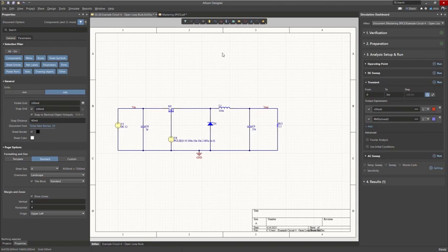So now let's say that everything is good with this design, and we want to make thousands of this design. We want to produce them. So what we want to be wary of is the varying values of my components, because when you get components, they're not always as labeled. For instance, a 100 ohm resistor, if you're ordering thousands and thousands of these components, maybe one will be 100, another one will be 97, another would be 103 ohms. So they're not all going to be the same, and that's true for capacitors, inductors, any other type of component you're using.